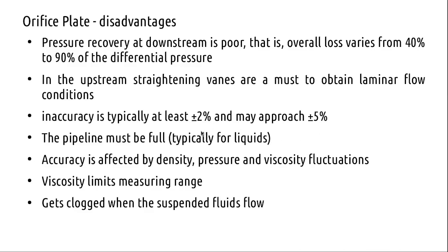It's going to be inaccurate to some extent, 2% to 5%. The pipeline should be full. Viscosity is going to affect your measurement. You can imagine using an orifice plate to measure a thick fluid flowing through it.